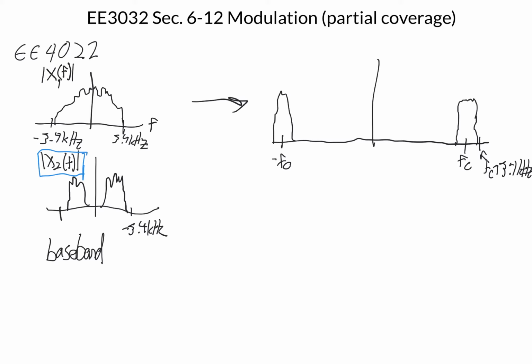What if I put another carrier frequency slightly below the first, so let's call this FC2, and I take X2 and move it up to that frequency. So I have this spectrum here, and minus FC2 here, and we're going to have the mirror image. As long as these do not overlap, they can share the bandwidth, they can share the wireless spectrum and be transmitted together. So this is one of the simplest forms of sharing multiple radio signals.